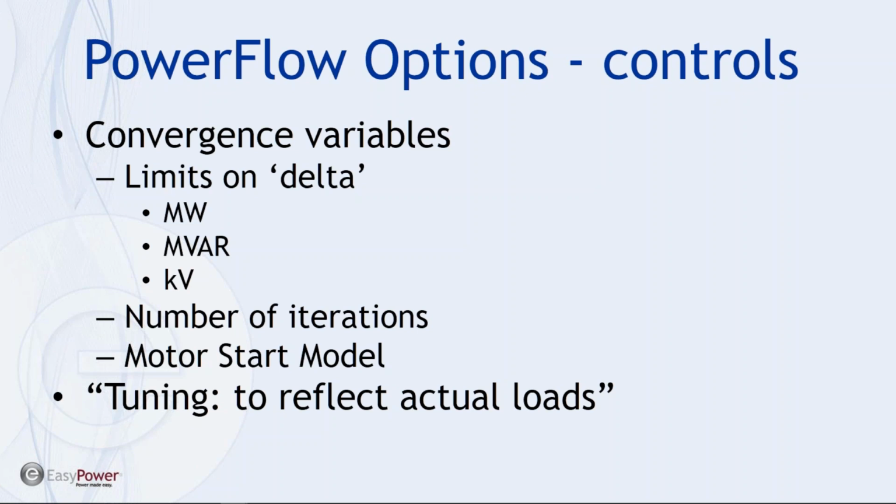In addition, we're going to talk about tuning, because that's probably first and foremost the best way to modify the model that we use for ArcFlash analysis or short circuit analysis, because it's more ideal and based upon nameplate data, whereas the PowerFlow will be based upon how the system's actually operating, which may be far different from the total design limits of the equipment involved.